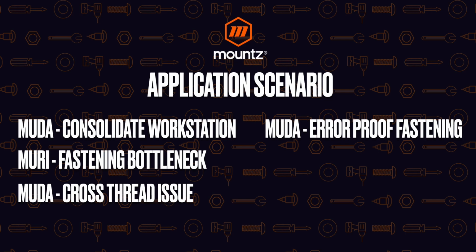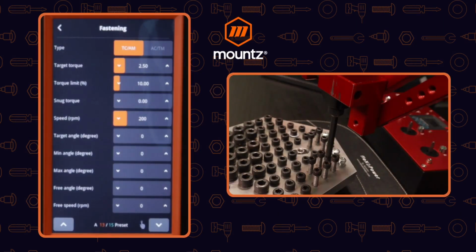And so we're coming back into the parameter menu here, and we are dealing with preset 13. What we want to do to error-proof the assembly is, if the operator does get a cross-thread event, we want the tool to be able to tell us that that has happened.